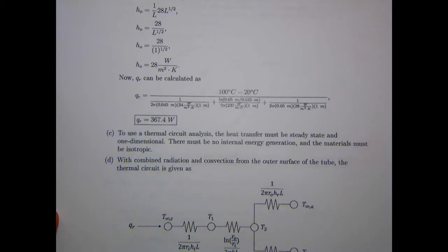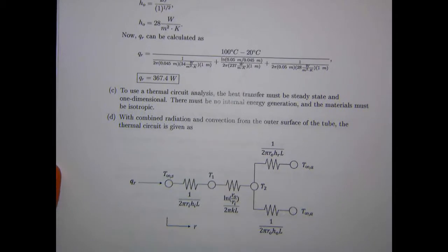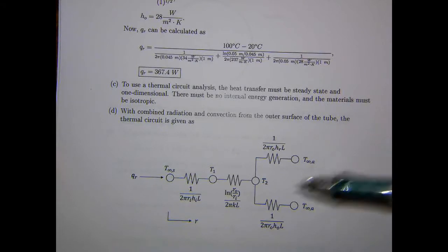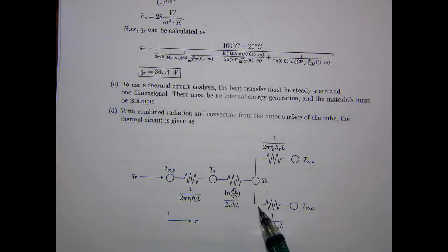And then on the last part, just not solving for radiation or anything, but just saying, okay, now we have radiation on the outer surface, and that's just going to mean that it's convection and radiation in parallel. So just changing this last part of the thermal circuit.